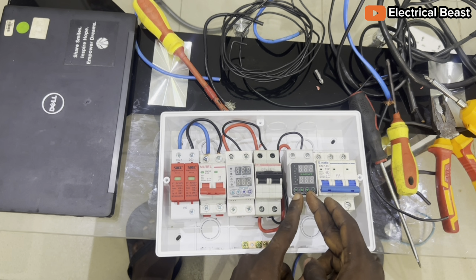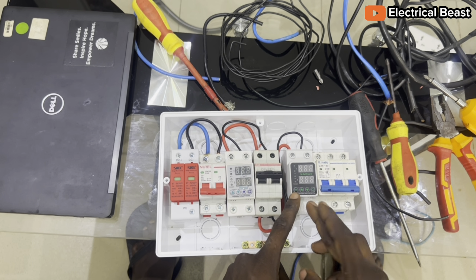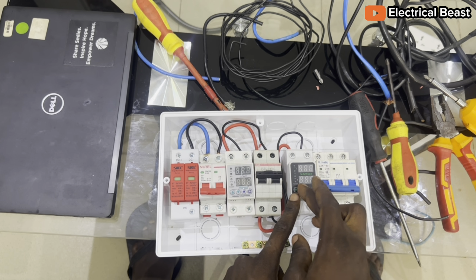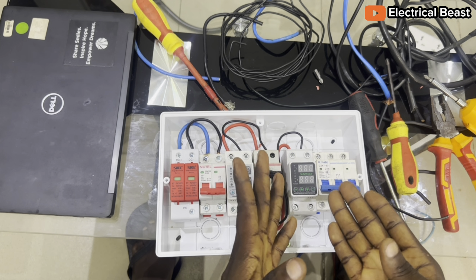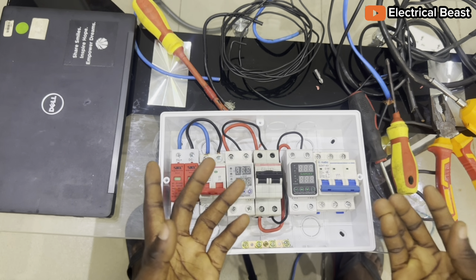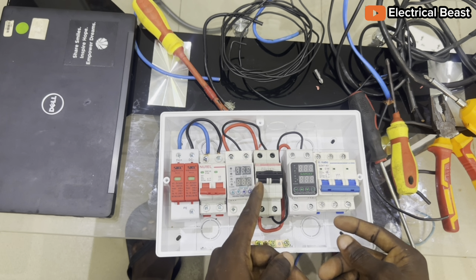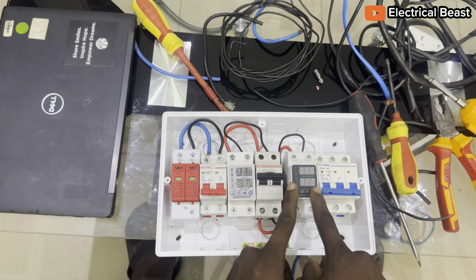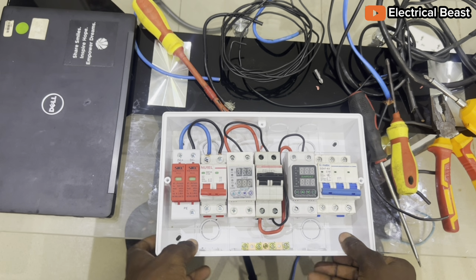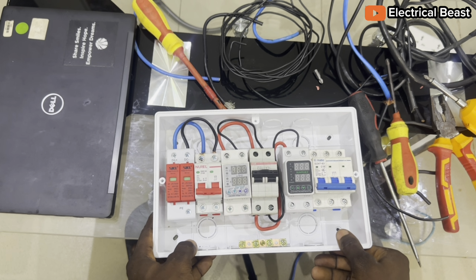But if the AVS comes first before this breaker, if there's an over voltage or under voltage, and even if the voltage has dropped and it's not able to reset by the settings you did, it's just going to remain like that. So most times you have light and discover that nothing charged the inverter or the battery when there was light. So to avoid that, you need to connect the breaker first before you connect the AVS, to avoid all of that disappointment. Okay, so I think you understand what is going on right here. So this is how to connect it, nothing more, nothing less.